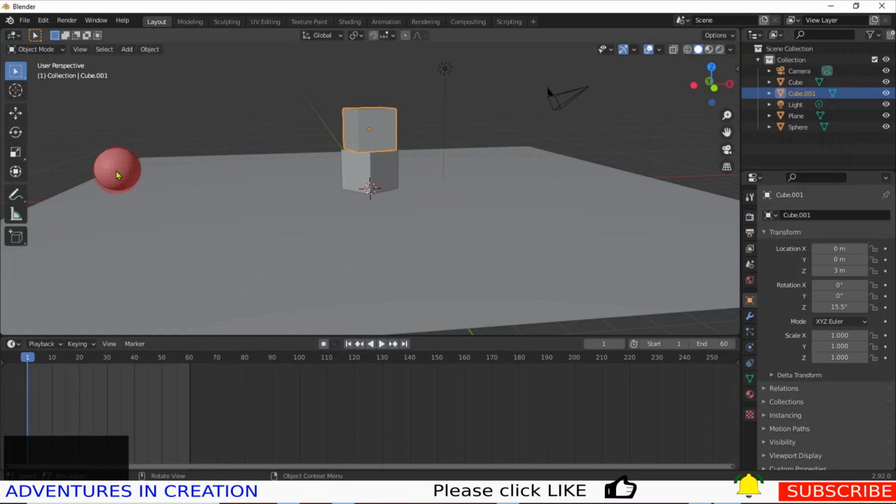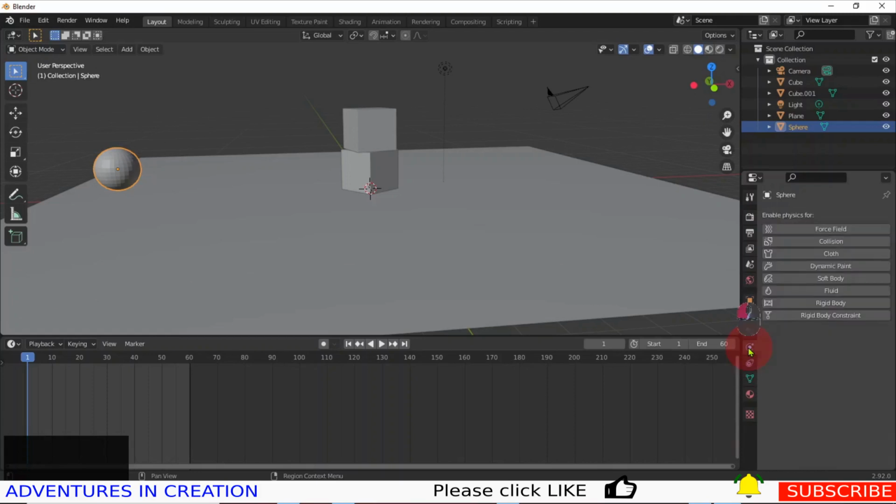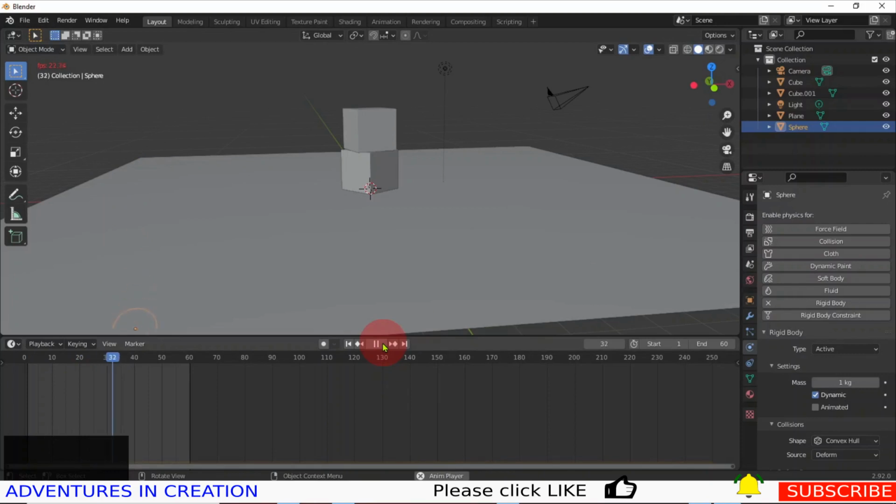And I'm going to take this ball and we're going to add some physics to this ball. So what we're going to do is go over here. If you look on these icons, I showed you before that this one is the object properties. This one, it looks like, I don't know what it is, a rod with some kind of movement around it, I guess, is physics properties. So if I click on that and I say, this ball is going to be a rigid body. So I just click rigid body, don't do anything else. Now, if I press play, see how the ball falls to the ground? Or it actually falls into space.